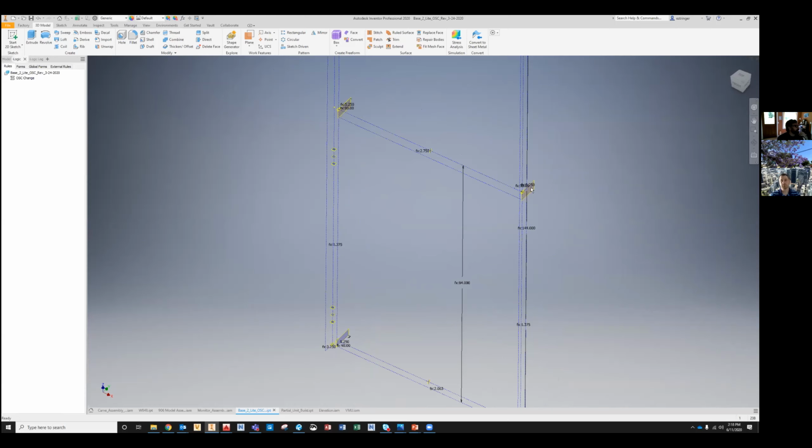Depending on how the wireframe is configured, you place them where they're appropriate. Those can then be used to set up a unit configurator, where you can set your unit type, the mod width and mod height, and the placement of the intermediate horizontal. There are a lot of little things in here that you can adjust. They aren't necessary, but it's nice to have because it lets you take one model, adjust it a lot, and get a lot of very unique units out of it. I'm going to take you through the process of doing an extrude, and then I will show how the configurator works on a model that's been partially modeled because it shows it off better.